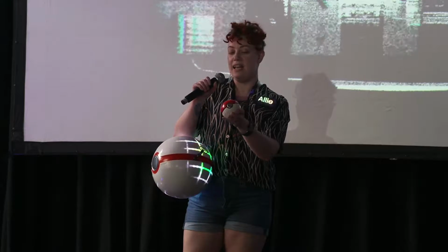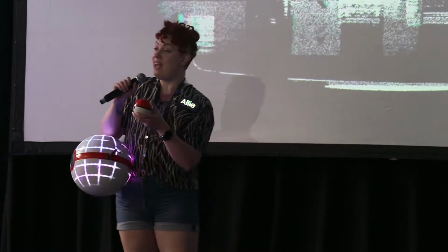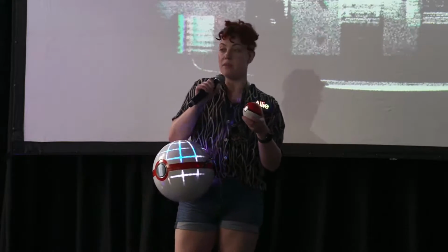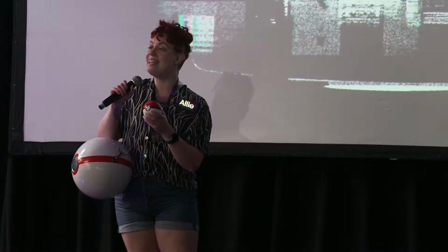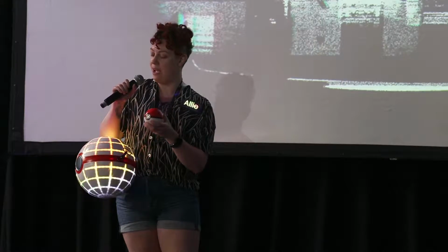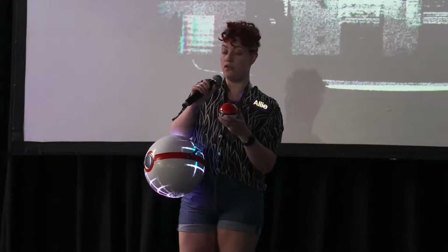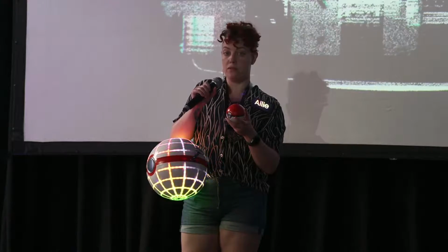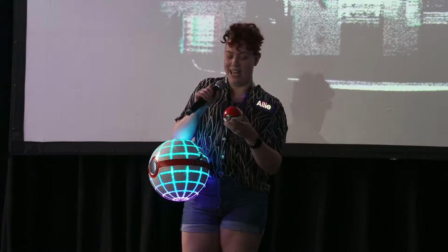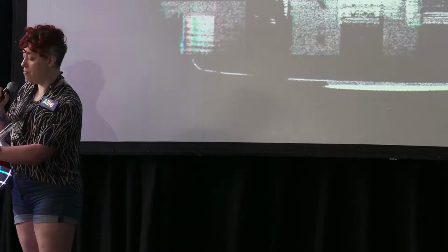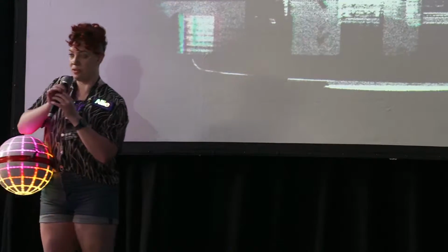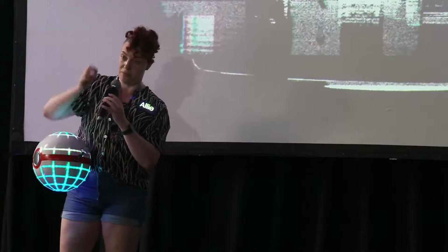That's it. Now, I will say, and this is one thing I haven't been sharing with people, there are very much tips and tricks with smoothing PVB in that it very much takes time to settle. I have learned the hard way that if you go too hard too fast with it, it basically melts, because that is what it's doing, it's melting. And if you do it too quickly, it will just melt too far and you'll get bubbles and it won't actually be smooth. It'll then just look like garbage.